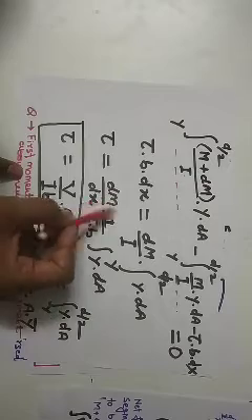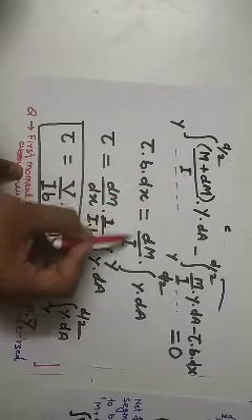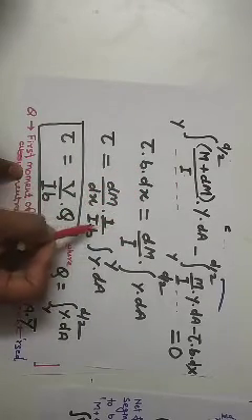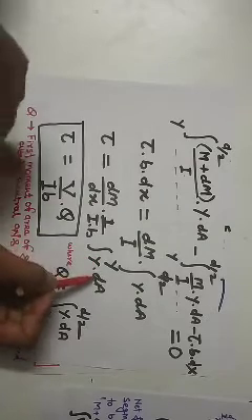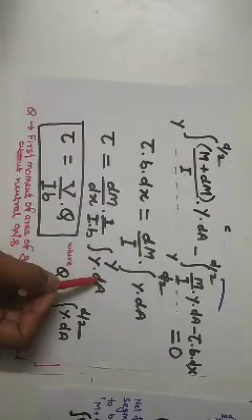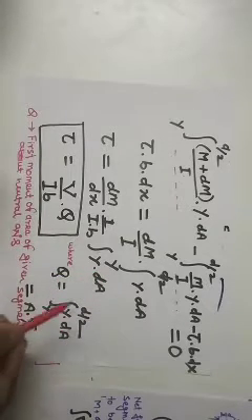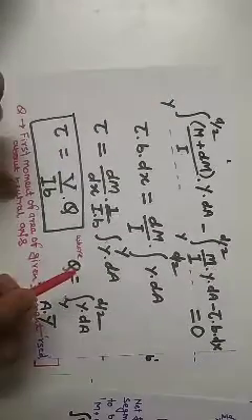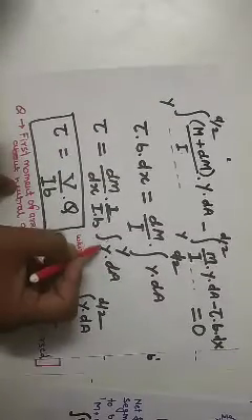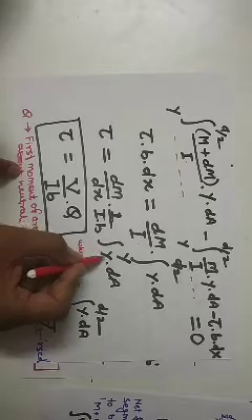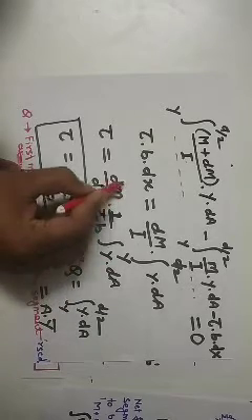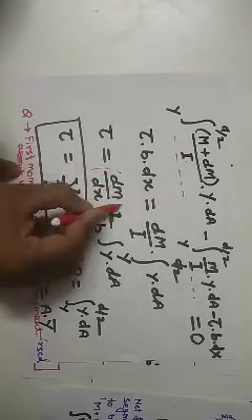Now dM/dx, transferred over here, gives (dM/dx) times 1/(Ib) times the integral of y dA. This integral of y dA is known as the first moment of area of segment RSCD about the neutral axis. Clear? And it can be represented by Q.